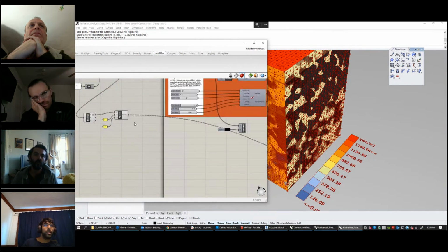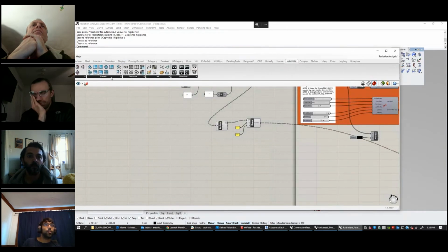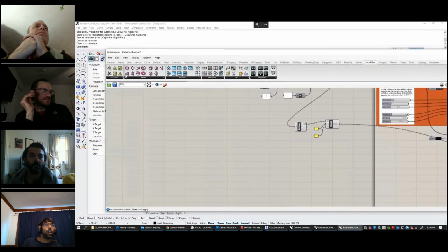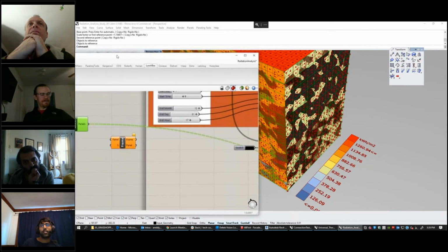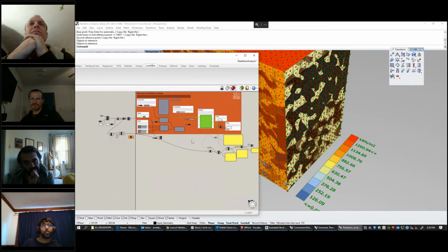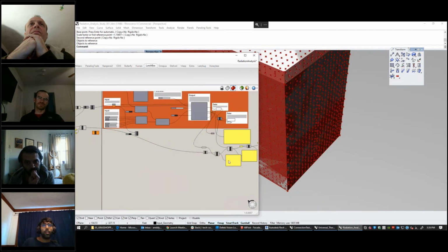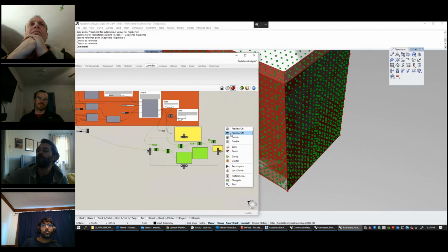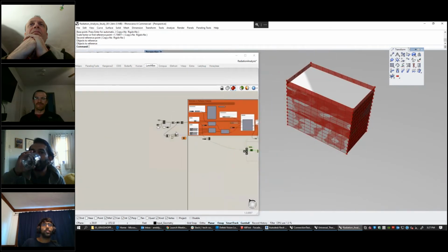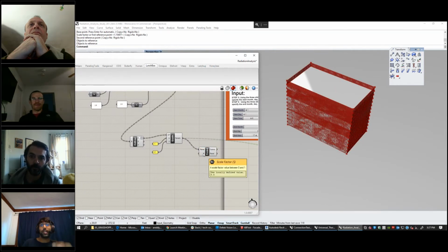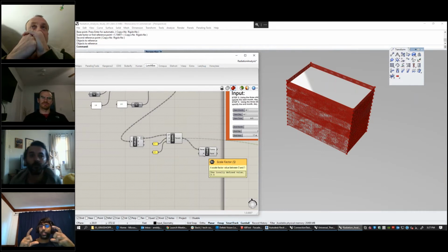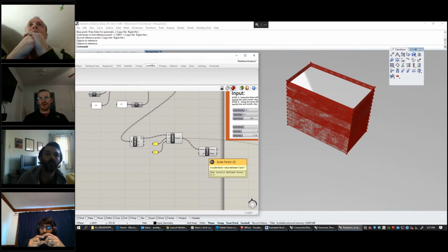And then let's go back to these panels. So Lunchbox has a really nifty offset panel frame command, right? So we take all our panels that we had before, all these guys, these square guys. I'll turn this radiation analysis off. Maybe all these tests, right? So we've got all our panels, and we want to slap some frames on it. And so it's looking for a scale factor between 0 and 1. So the bigger the scale factor, the closer it will be to the full size frame. So the smaller the number, the smaller the frame, right?